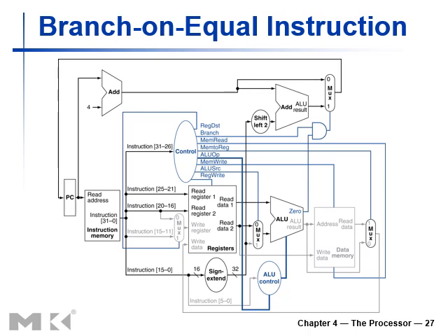And we have also discussed the limitations, not in detail, but in general, that the performance is limited by the longest instruction, and the clock cycle time is determined by the performance of the longest instruction. That is, in our case, the load word instruction. We have to set the clock cycle time according to the slowest instruction, and the slowest instruction determines the critical path of the system, and we have to find the critical path.